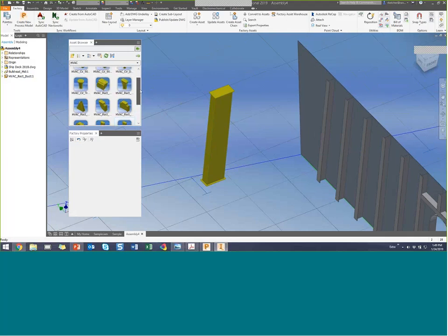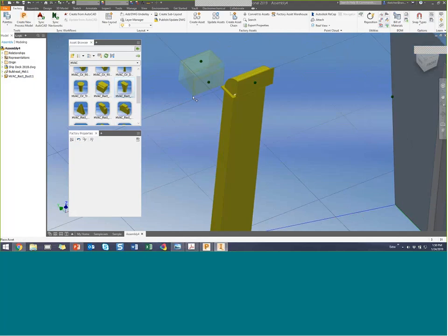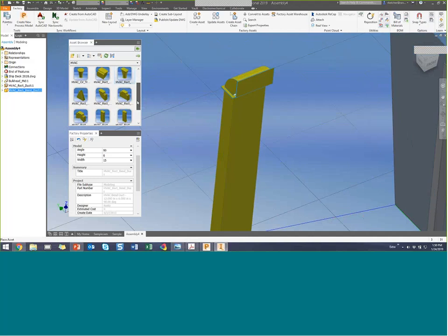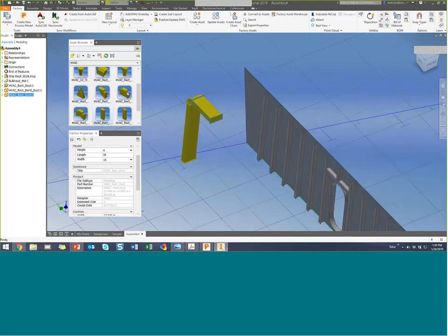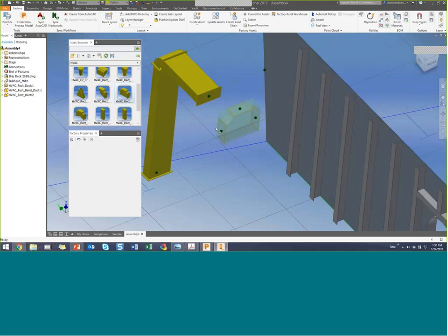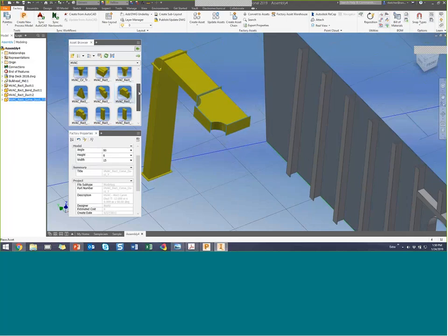So look how easy it is for me to do an HVAC layout. I can actually snap these components together. You'll notice that they actually resize themselves. So if I pause for a minute, you'll notice it's too small at first, but it resizes automatically. Let me grab a T-junction. We'll drop that in place. Let me grab a couple of flat curves.